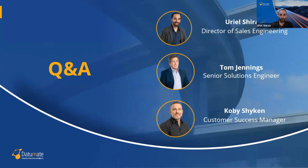So, Tom, I wanted you to explain maybe to our participants that don't know exactly what RTK is and what it allows, how it differs from standard GPS. Yeah, so standard GPS is accurate approximately to 1 to 5 meters. RTK stands for real-time kinematics. And what that does is it greatly improves the accuracy of the drone data by reducing that unknown down to just a few centimeters.